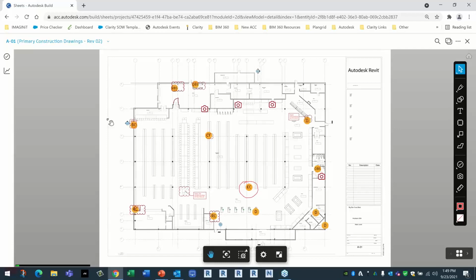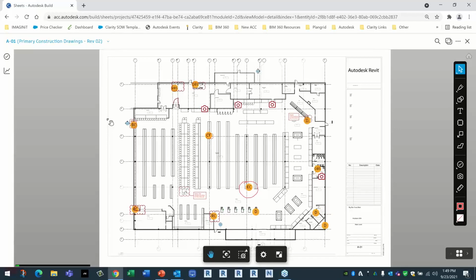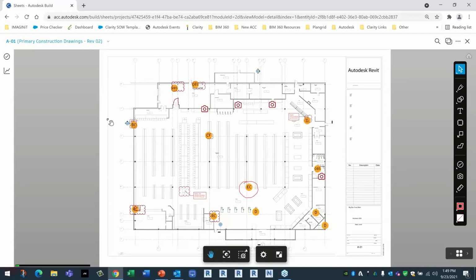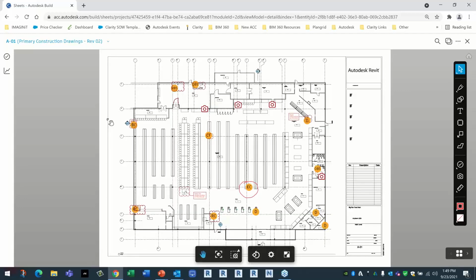Now, of course, he probably is going to print PDFs to get stamped to store in City Hall, right? You've got to do that. But after that's been done and we have that official set, he is just publishing it directly within the system with a single button click. All he has to do is it scans the sheet numbers, and usually you just have to hit yes, yes, and you're done, and everything's ready to go. Especially when it's coming from Revit, it's much easier than when you're trying to print to a PDF first and then go in. So now I have all my sheets.